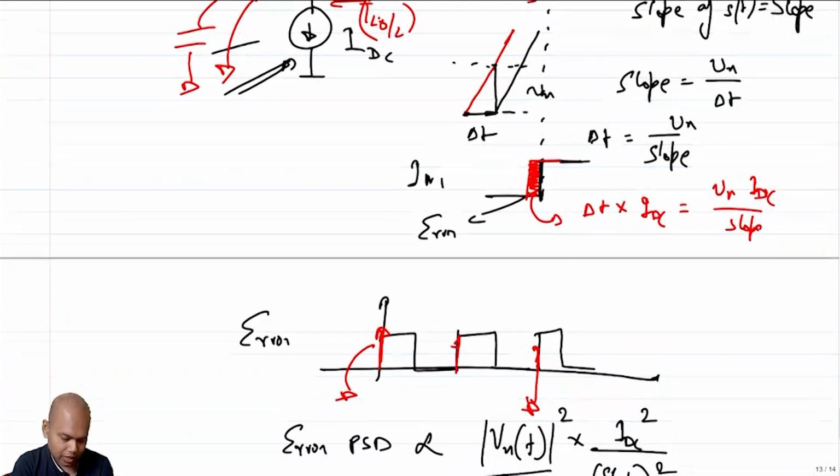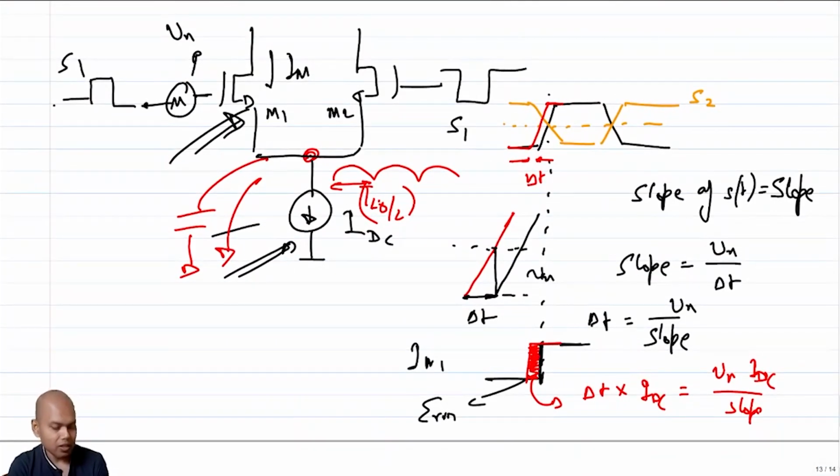So that is something that again you have to be careful of. So the crux of the story is you get gain using active mixers, but at the cost of flicker noise and power. You do not get gain in passive mixers, but you also do not get flicker noise, right? So that is something that you have to be aware of.